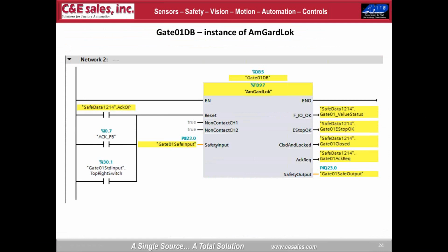So this is how I actually entered that function block in the ladder diagram. You just see that I can reset it from any one of 3 places, and then there's a few fail-safe outputs I chose to annunciate directly from it.